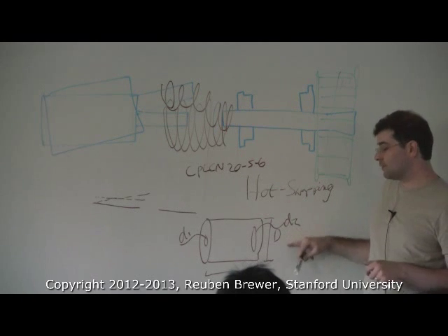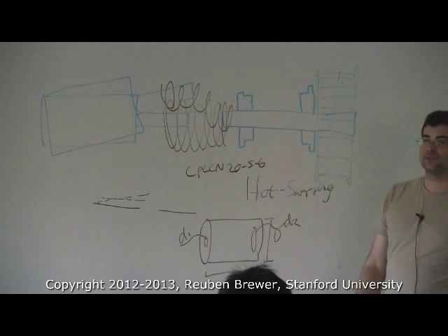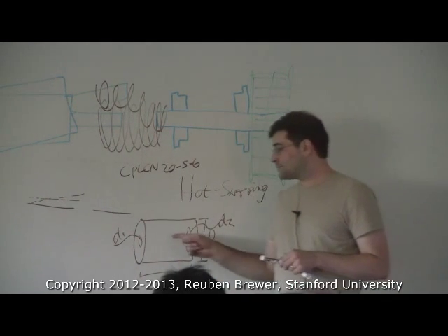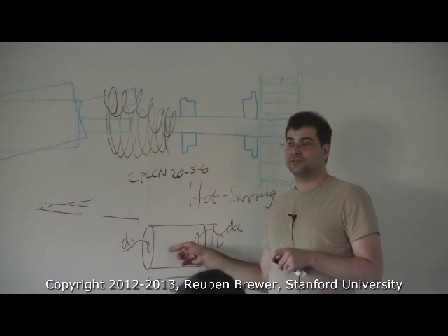The 20 is the overall D. Now, depending on the manufacturer, the part name might also include L. They have set screw versions of these. They suck. Try not to use them.